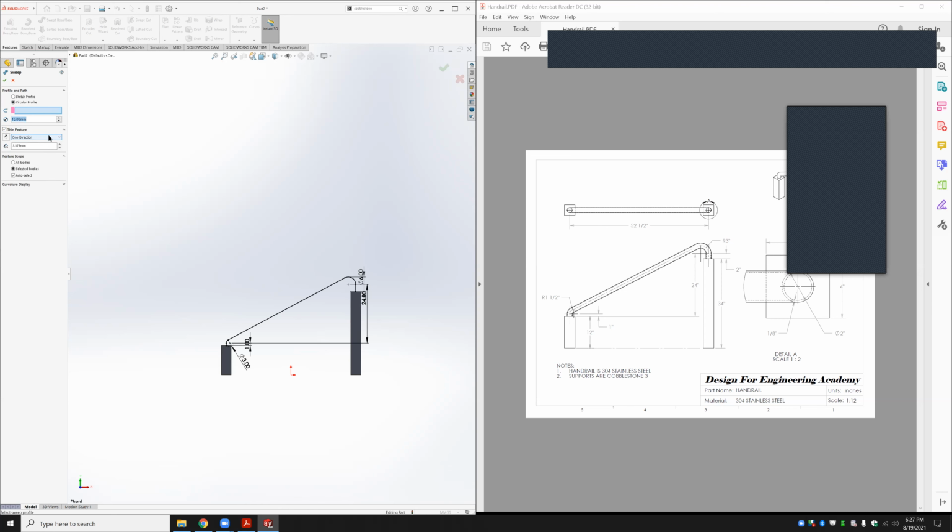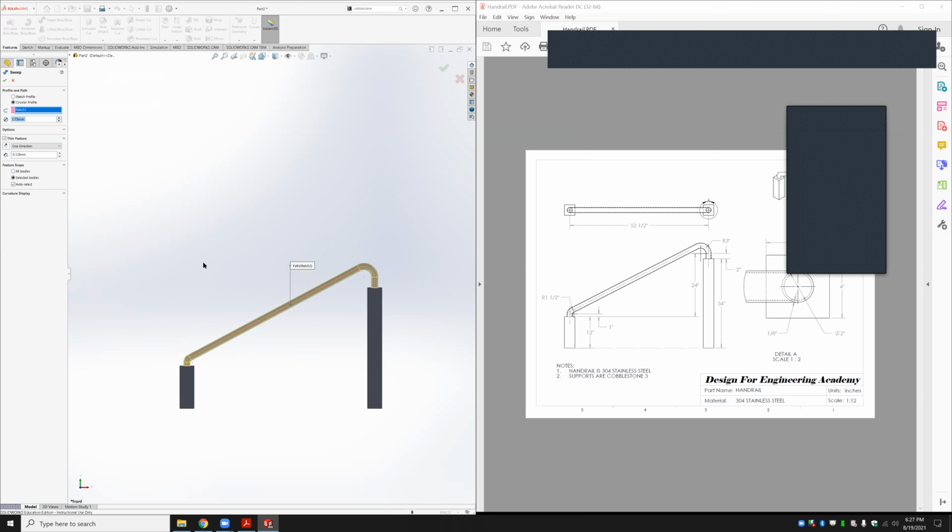And my inner diameter, if you look carefully, this is giving the inner diameter. And I messed up on the math twice on this one, but the inner diameter, because we have an 1/8 inch on both sides, 1/8 inch times 2, it's 1.75 exactly. And then for the thickness, in this case it's millimeters, but we'll fix that at the very end. That would be 1/8 of a millimeter in this case. So when I need to pick the path, there's my path right there.